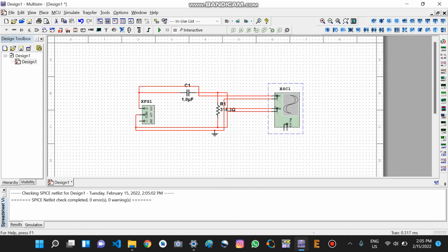Here the capacitance is now acting as a short circuit for higher frequencies. The capacitive reactance formula is, as we know, X is equal to 1 by 2 pi fC. Now as f increases, f is 10 power 6, the reactance is very low. Very low reactance means it is a short circuit. Now all the input voltage is coming across R1, so the gain is almost 1.